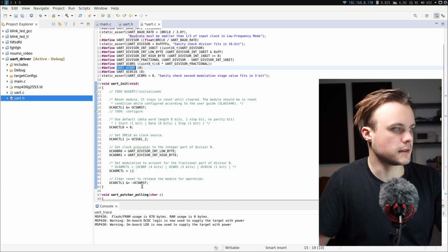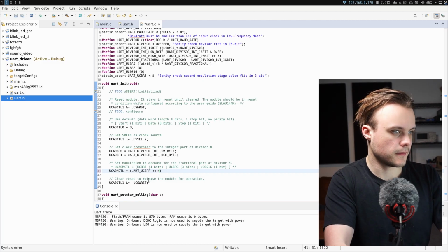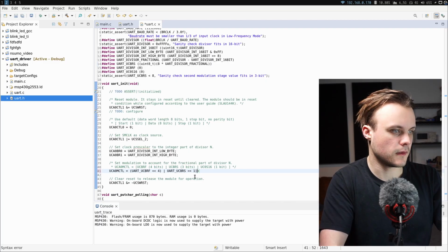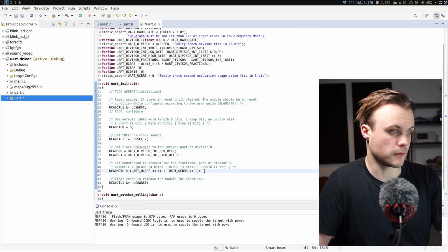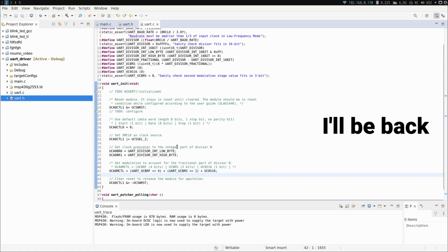And then, since this is the 4 most significant bits, I'm going to shift this 4 steps. And then this one, I only have to shift 1 bit. Use a plus here, doesn't really matter. And then finally, I could just remove these actually, since they are 0, but I will leave them here for clarity. And this is everything I need to do to configure the UART to a baud rate of...